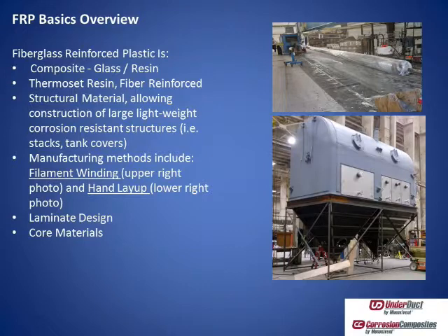To allow for hanger spacing, or in the case of what you're looking at in the upper photo, that's a light pole, the winding is stretched out, so to speak, and resembles a Chinese finger trap, but the angle gets longer. And that gives you some axial strength so that you would require fewer hangers. So it's a combination. Filament winding alone can be hoop winding, which would be 90 degrees, or it can be what you're looking at in that light pole, which is probably about 50 degrees. So we can do a lot with just filament winding.